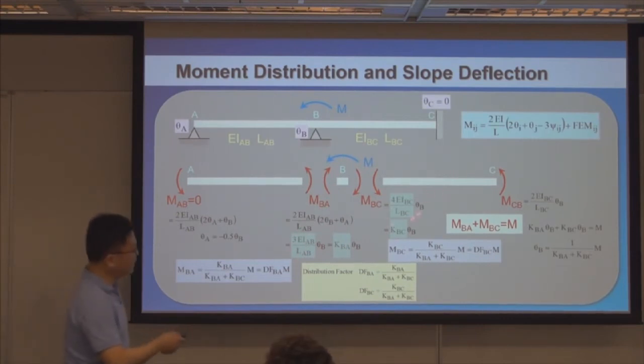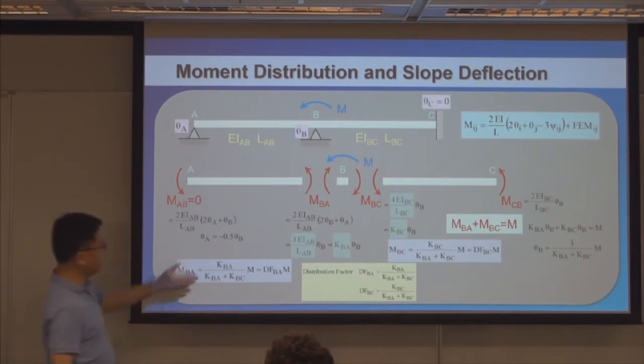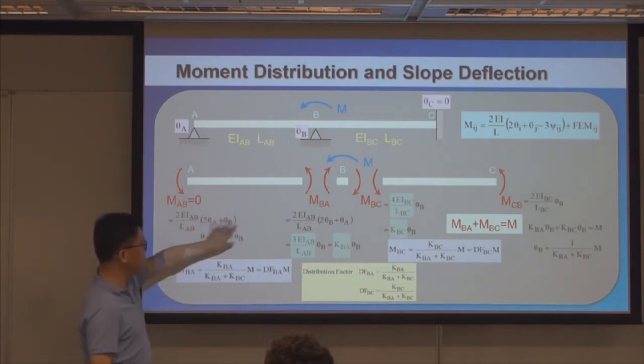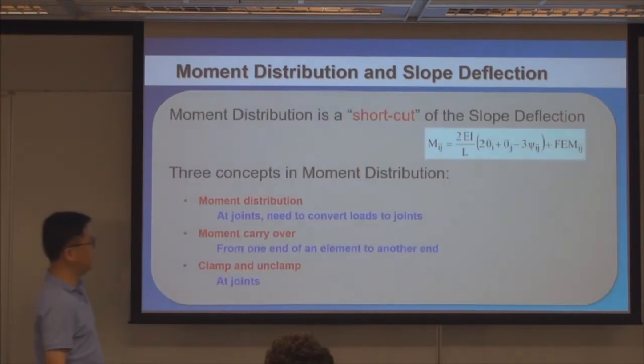Now, how about 4EI? It's 4EI because at that end, we don't have a moment-free condition to use. So there's no way you can reduce or amend this coefficient because there's no moment-free condition that you can use. So that remains 4EI. Okay, so that explains why one component is 3EI over L, and the other component is 4EI over L.